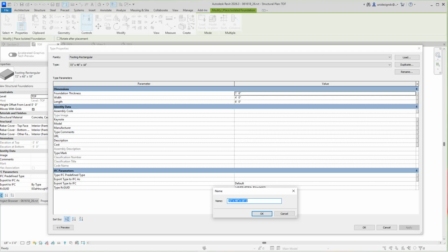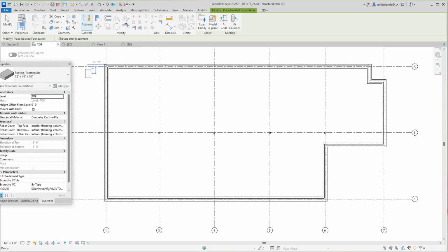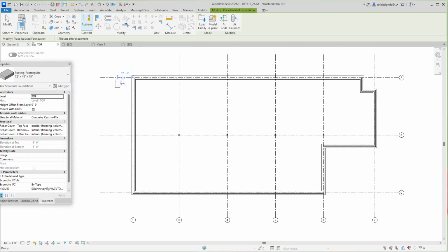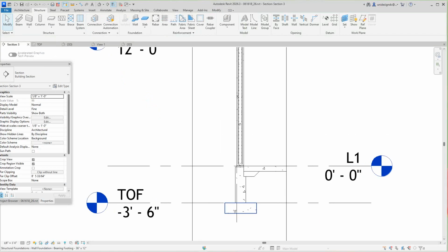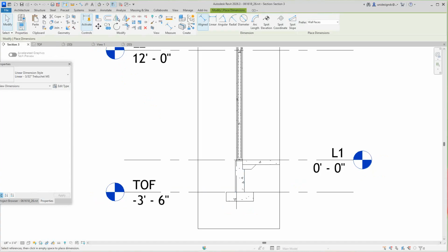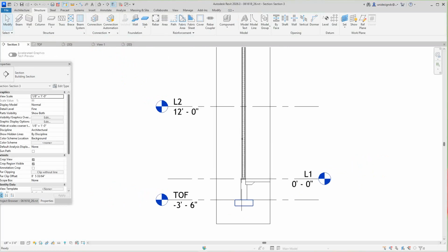I think we might want to match our footing on our floor. So let's cancel out of this for a second and just double check and see what this footing is on our wall, just to make sure we're consistent here. So I'll go back here, and then we're going to check this size here. Actually, we can measure it. It's 1 foot, so I think I want to make that a little deeper than a foot. But just for consistency's sake, let's make it a foot.